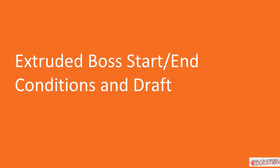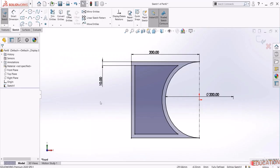Extruded Boss Part 2. We need to create this sketch. Basically, it's half a circle here, and a horizontal line, and it's tangent, and it's coincident with the quadrant point, and the same one as here, and then you need to connect them, and finally you need to offset this inside with 10 millimeters, taking into account these dimensions. It's very important to have this line as a construction geometry. Otherwise, it will cause you a problem when dealing with Extruded Boss.